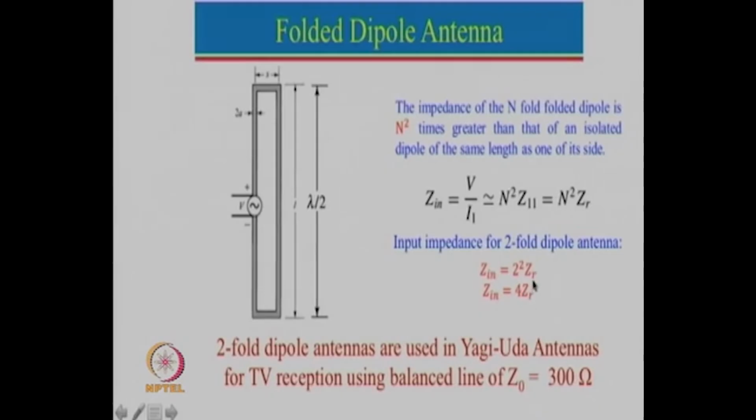In fact, this has shown just the real part here, but that will be valid at the center point. So, let us say the impedance is equal to 68 ohm, then you multiply that by 4. So that will be the dipole antenna input impedance at resonance frequency. But off resonance frequency, this term will become a complex number.